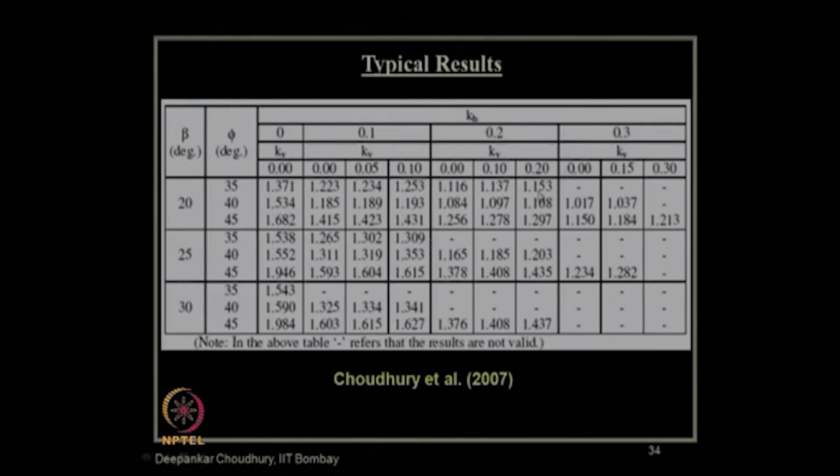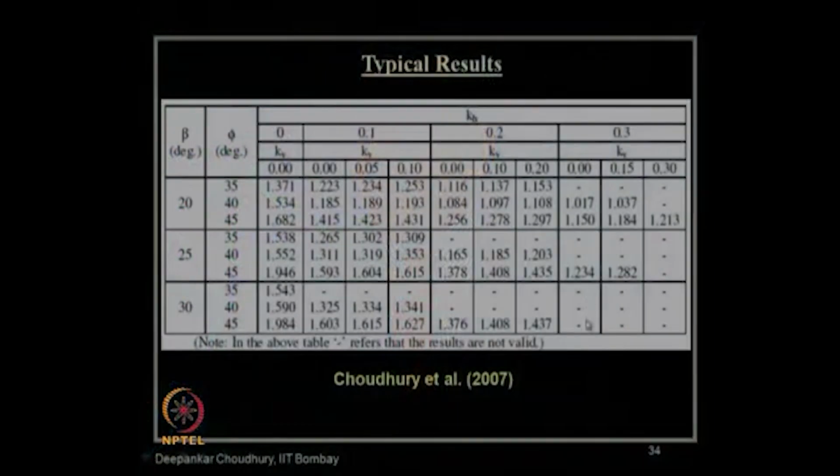That can be seen very clearly. In both cases, it is going to give us a more critical state, or more towards the unsafe side, when the seismicity value increases in terms of horizontal and vertical seismic acceleration. And this dash value shows that this is not a stable condition in terms of shear fluidization criterion or stability criterion.